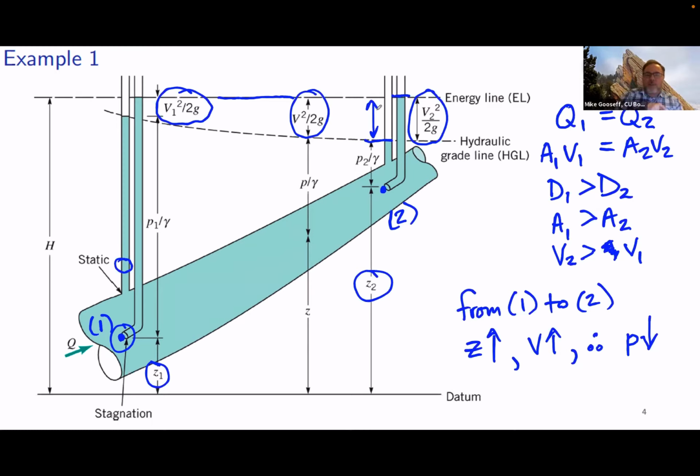It's when we apply the Bernoulli equation right out in front that we would say that V is equal to 0 right in front of it, but that head is still being provided up the tube. Let me think of a better way to say that. So the streamline that moves along the center, I guess I can actually draw that. So the streamline that comes along here has to end up splitting, right? Part of it either has to go above or below or around to the side of this stagnation tube.